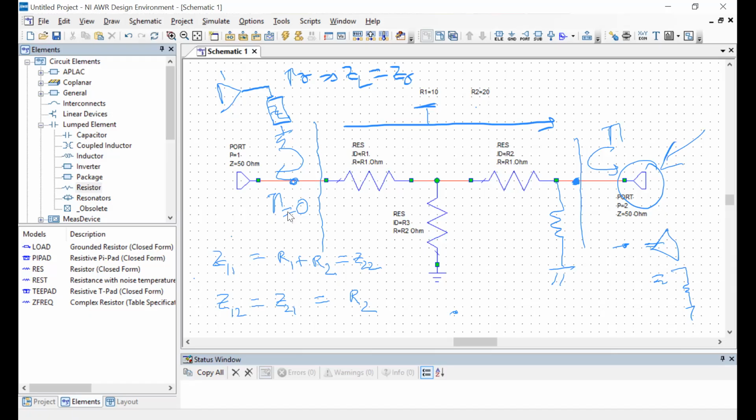When would you say that the circuit is working properly? Because you can actually make a mistake here. You buy this attenuator and you say, let me check if it is giving me a small gamma, because you will never get gamma equal to 0.